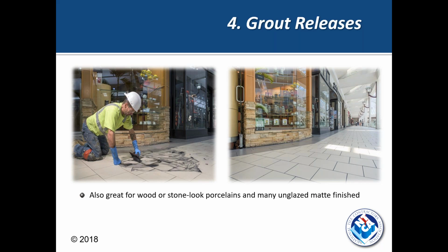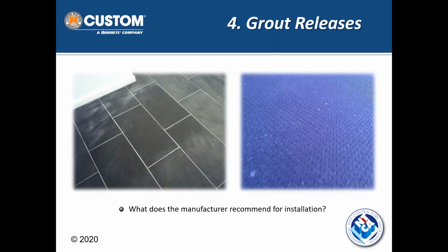So again, these are not sealers, but they are temporary barriers or film formers that allow the installer to do the job with the right open time and working time and the characteristics that you're supposed to get from the grout, but also it does not allow for that staining that we've shown and talked about. And again, you see the during and after picture here. And that's what we want. We want to make his job as easy and profitable as we can, without the headaches and hassles and all the meetings and why did this happen and whatnot, right?